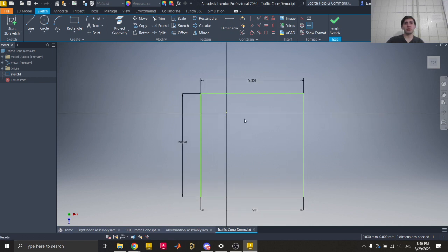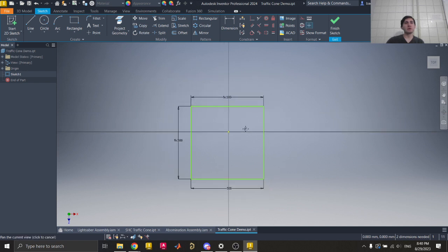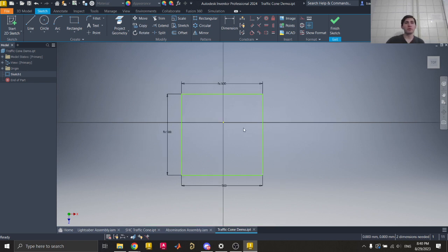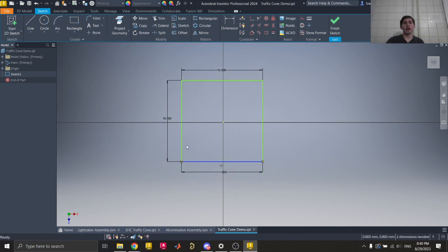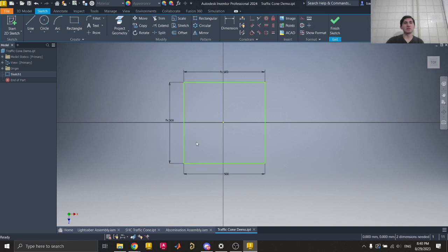One thing you can also see, we're not quite centered with the origin of this drawing. You don't always have to be, but it is good practice to stay reasonably positioned around your origin in some logical way. So one way that we can center this, we can use some additional dimensions where we dimension some of these lines in reference to this center point right here, the origin. It is possible to drag these a little bit and eyeball it, but it isn't quite exact. You're always going to be at least some amount off.